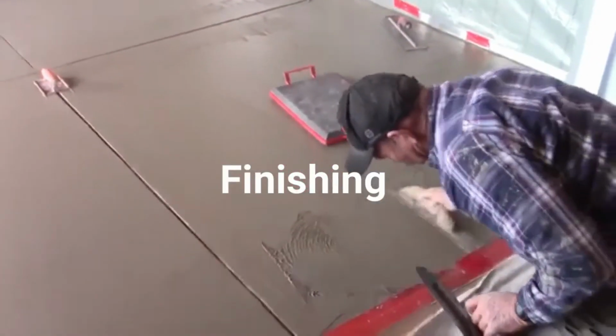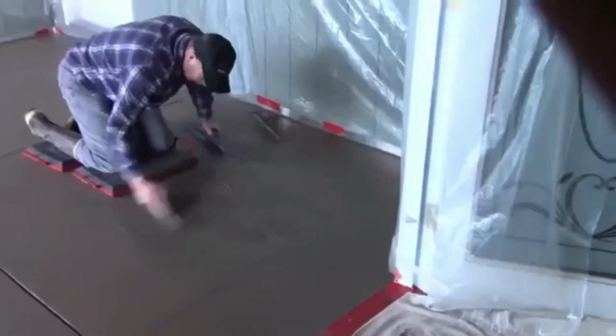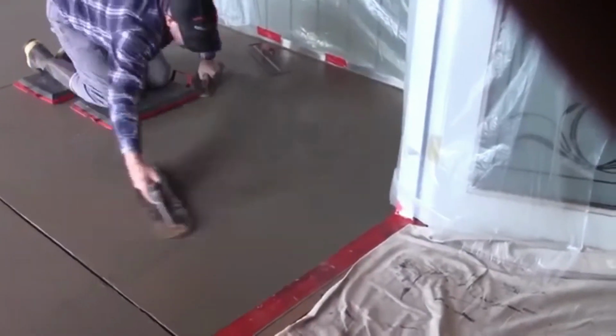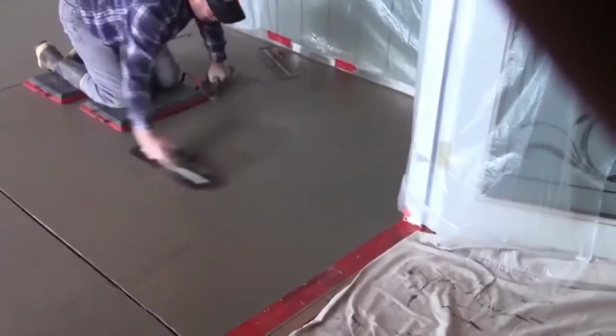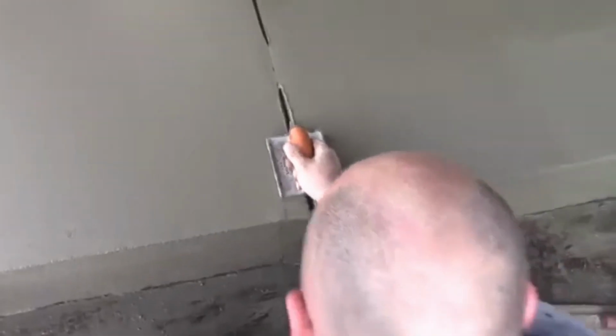Finishing. Usually a smooth finish like that found on a sidewalk is needed. A smooth finish is called a steel trowel finish. The finisher makes it by moving a steel trowel back and forth over the surface. A troweled surface can also be made with a finishing machine.